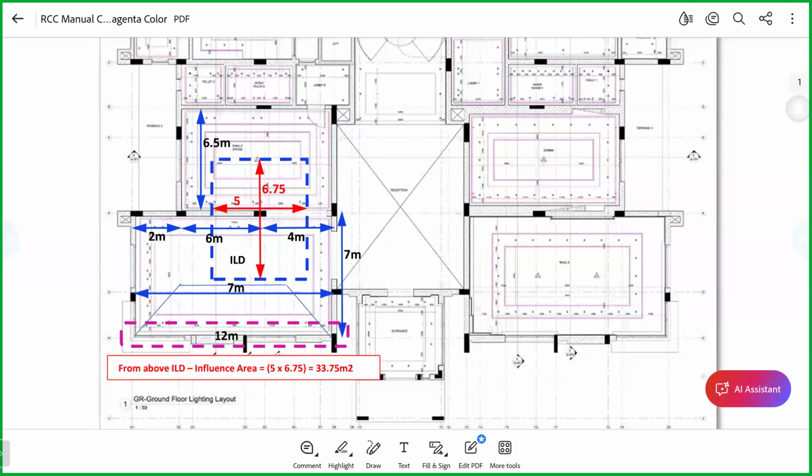Actually, remember, when you talk about loads, there are two kinds of loads. One is gravity, another one is lateral load. Don't tell me that when you talk about loads, you're talking about dead load, SDL, live load. There are only two kinds of load. One is gravity load, another set is lateral load. So under gravity is actually dead load, SDL, live load. What is SDL? Superimposed dead load. Okay. Dead load is the self weight of the particular structural element.